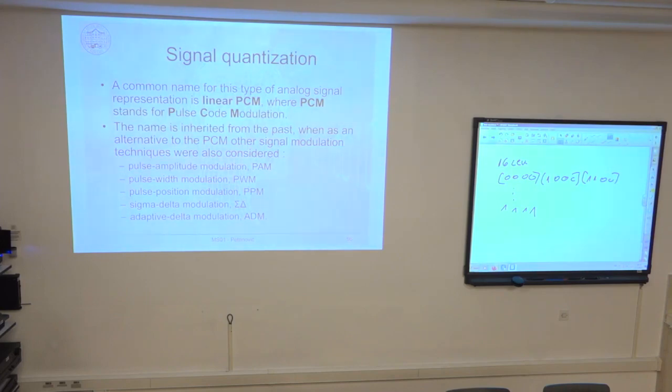And this part is analog. This sigma delta modulator is analog circuitry. And only after that you have the digital part that operates at the oversampled rate, but it starts with only 1-bit precision. So the trade-off is between the oversampling ratio and the resolution. So the basic idea behind oversampled AD conversion is the trade-off between sampling rate and quality, that is, amplitude resolution.